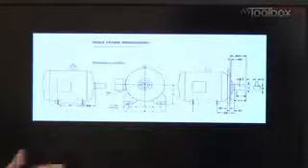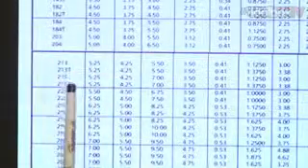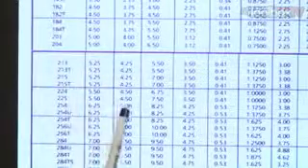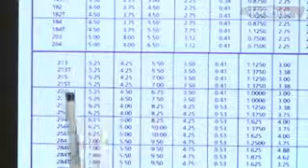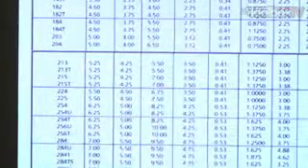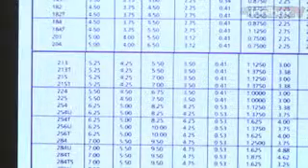Let's take a look at what those equate to in the chart. If we look at a chart, 215T is right here, and dimension D, that was the shaft height, is in this column. So the shaft height of a 215T motor is 5 1/4 inches. I think we also looked at dimension 2F, which was the hole pattern down the length of the shaft. Dimension 2F for that particular motor is 7 inches. So using these tables, if you had to drill motor mounts and mount the motor, you would know exactly where the holes would need to be. So all of this is just mechanical information.